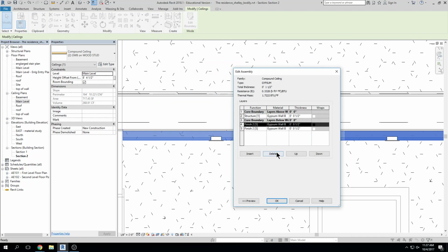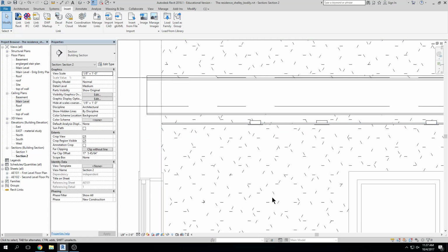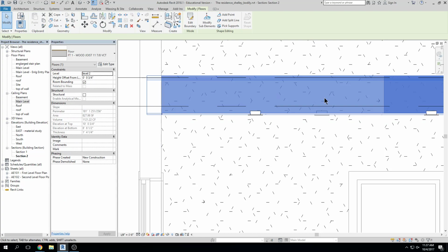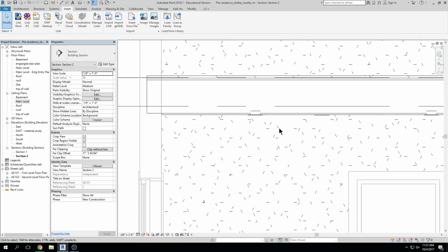I'll click on that, delete, click on that, delete, hit OK, OK. There's just my gypsum board. AL, align, click, click. Don't forget that you added gypsum board to the floor system, right? So we're going to hit edit, edit, and we'll remove that gypsum board. Delete, OK, OK, and there's your ceiling.